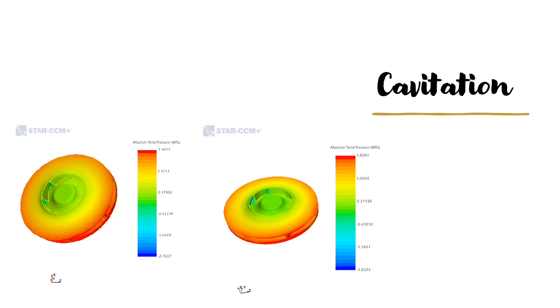On the other hand, it is crucial to verify if the pump's design presents cavitation. Cavitation refers to the formation of voids or hollows within a liquid medium. If the fluid saturation pressure is within the range of absolute total pressure, bubbles could be formed and some of the fluid can be evaporated. This damages the pump quickly.